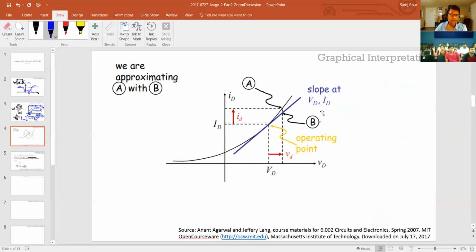And then I talked about a small signal model, and I gave a big long sort of motivation on incremental analysis, why we do small signal. And as I said in the lecture, it's trying to linearize a nonlinear curve, right? So for example, this is a diode curve, it's nonlinear, and it's harder for us to do analysis using nonlinear equations. And we said that if you know that your signal is a small signal around a certain point, then you can actually linearize the curve.